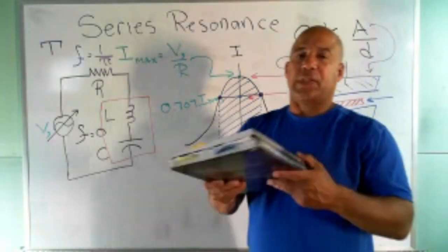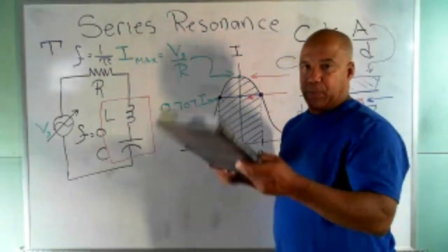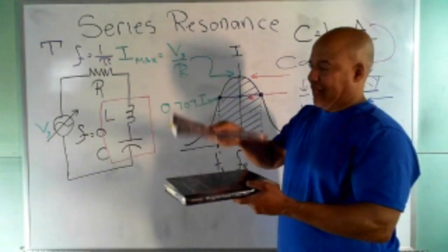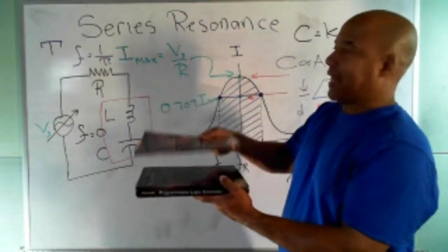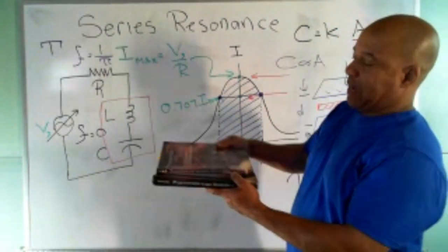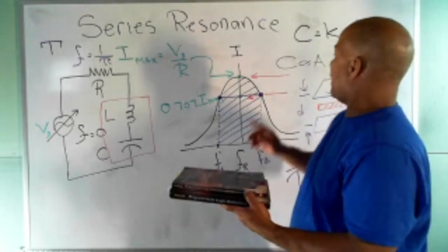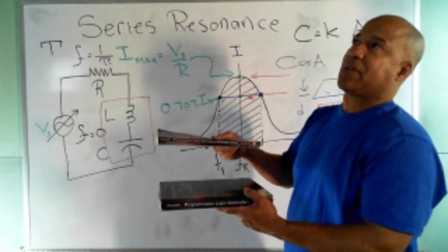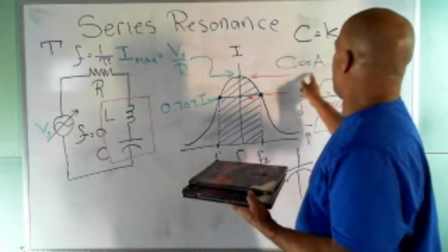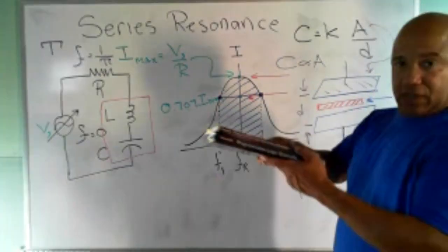But anyway, suppose these were metal plates. This book and this book, they're plates, right? And I got the leads connected to them, so I have a capacitance. All I got to do to use this formula is measure the distance between the plates, measure the area of the plates, and figure out my dielectric here is air. I think air has a dielectric constant of 1, so I just put a 1 in for that. If I measure this area and the distance, I can get the capacitance of this capacitor I'm holding in my hand.